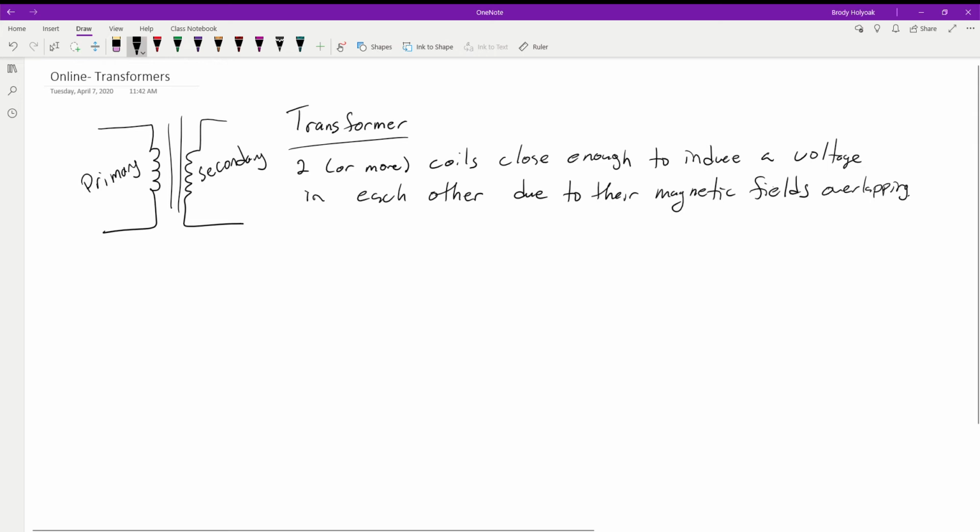If we only have, like, the generators that we have on our scopes, they put out a maximum of 2.5 volts peak. So let's say we wanted a 6-volt signal out of this guy. Well, we could use a step up transformer and step that signal up to 6 volts, which then gives us a better opportunity to use those. So that's another option, using those transformers to step up the voltage to get a wider range of signals.